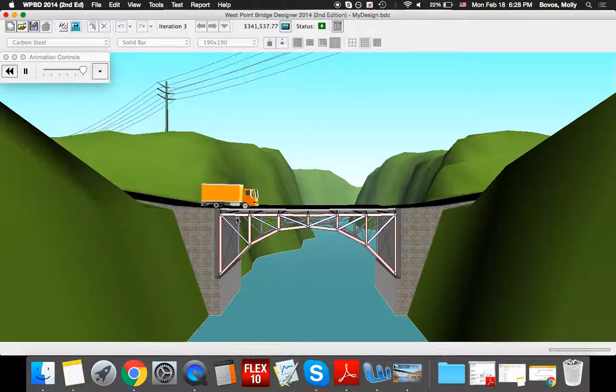So you can see here when the truck goes over this bridge, notice that these bars going around along the bottom, they turn kind of reddish. And what that demonstrates is a compression stress. These bars are actually getting squished together. It's hard to see in this particular one, but right here, there was some blue. And that blue indicates tension, meaning that those beams are getting stretched. Those members is what the beams are called. They're getting stretched.